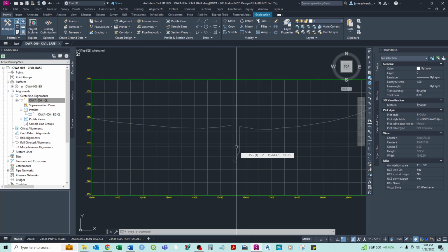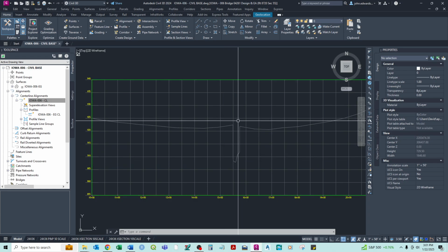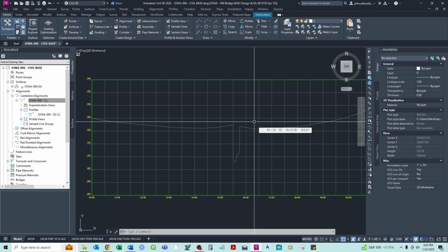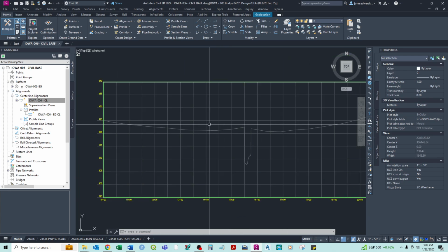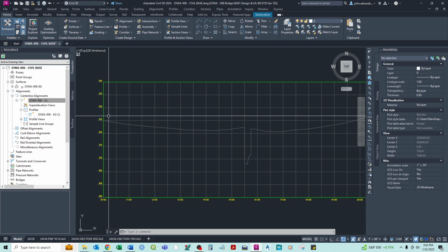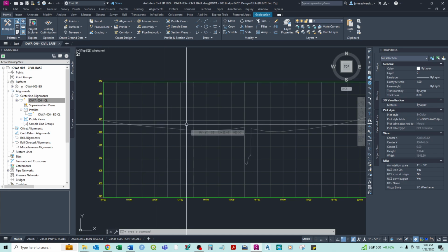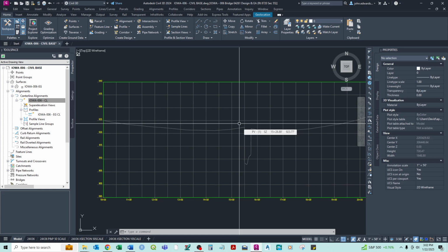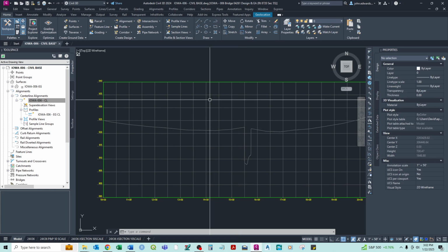Either you run the hydraulics or talk with your hydrologist to assess what options there are and what structure you need to put in. But prior to doing any of that, and just for reference, it's good to just lay out a basic profile. Normally the standard is try to match the existing. Most roadways, for the most part, you can follow the center line of the existing roadway, even if it's a full reconstruction or things like that. They're normally fairly close to what you want to keep.